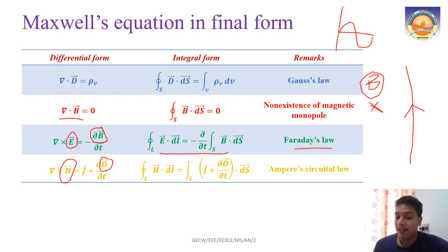That current will change with respect to the flux it is cutting, so that will be a time varying current. Whenever the time varying current is happening in the loop, again that will produce a magnetic field which will interact with the already existing field. So these two things, magnetic and electric field, happen simultaneously. That condition we call the electromagnetic field, or the time varying field.